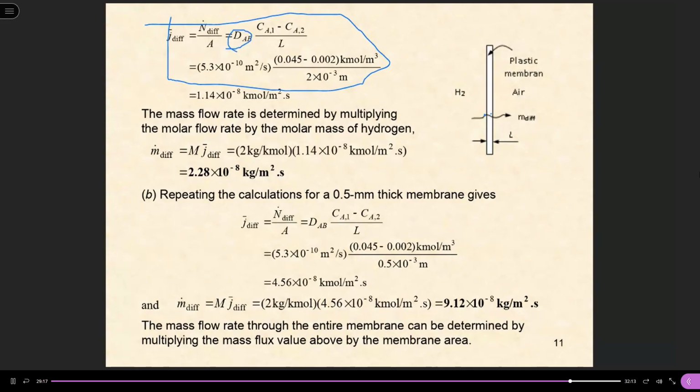But the point is, in this problem something given is not realistic. In reality, you don't know the fraction within the material. You only know the air side, the gas side information. So you would need to know the solubility of the material before you can do this calculation. So this is a very hypothetical problem. Why? Because as I emphasized, at the surface there is a relationship between the gas side and the liquid side. Typically, the concentration within the material is not known beforehand.